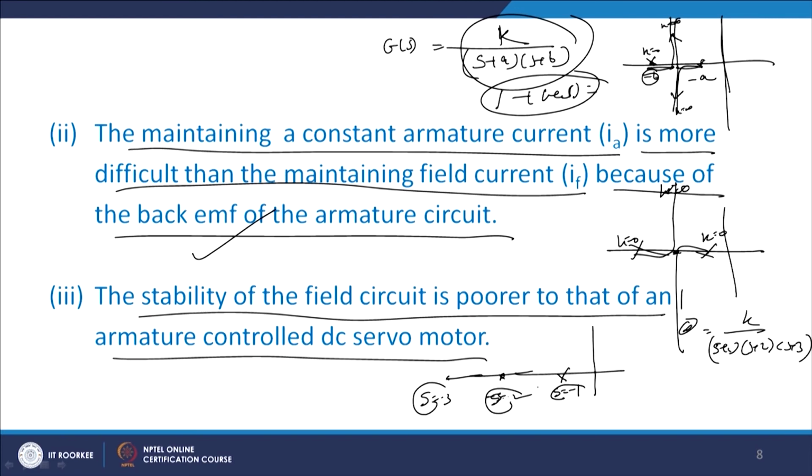In this case the root locus starts from a pole and terminates into a zero. So, one root locus is like this, and here one root locus from here will move like this, another will move like this. We will find that at some value of gain k the system becomes unstable. But a second order system is always stable.